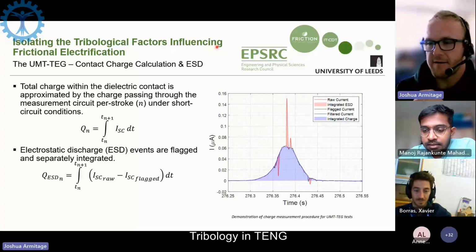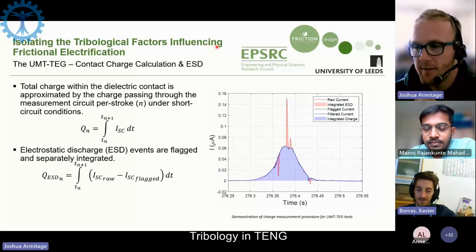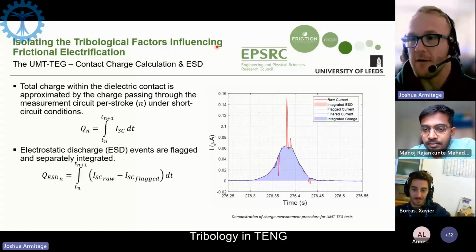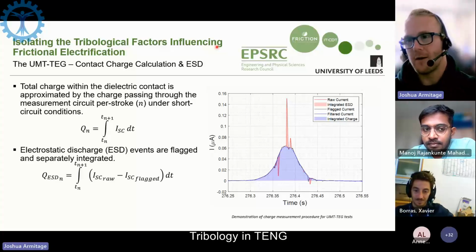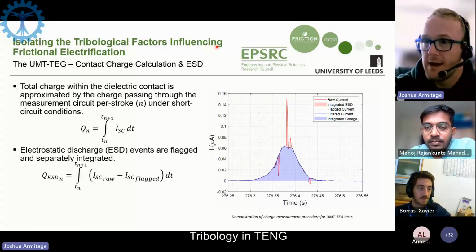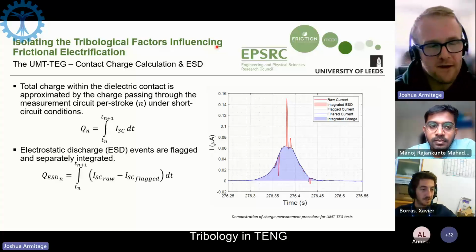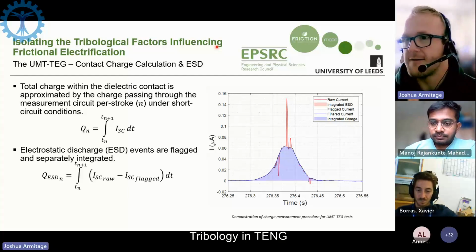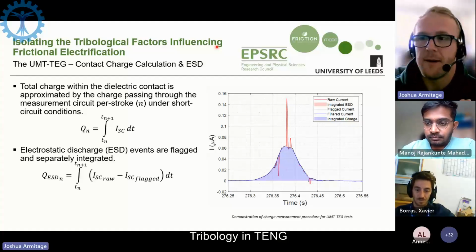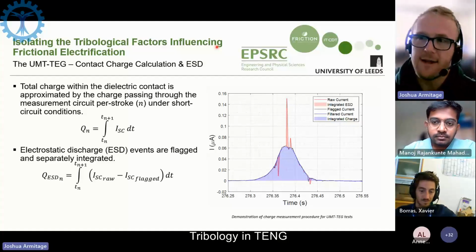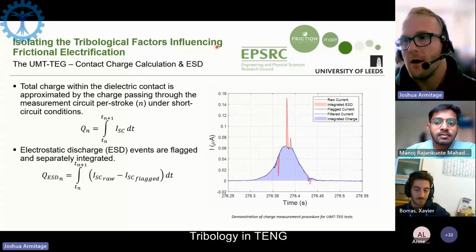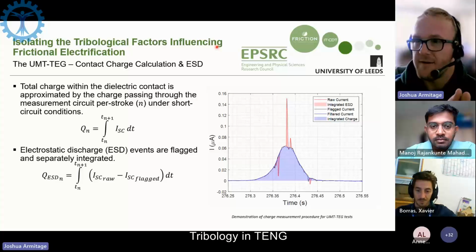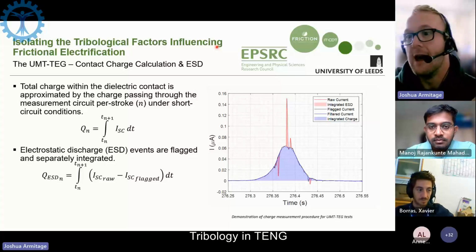So it's, is there any effect of frictional electrification on the tribological behavior? So where my research is looking at the influence of tribology on charging, the question is whether there's the reverse as well. So what we do see when we have these charged surfaces being contacted, we do have positive and negative charges being in very close proximity. So you would expect there to be what I would call a Coulomb adhesion between the surfaces, because we have these positive and negative charges in very close proximity.